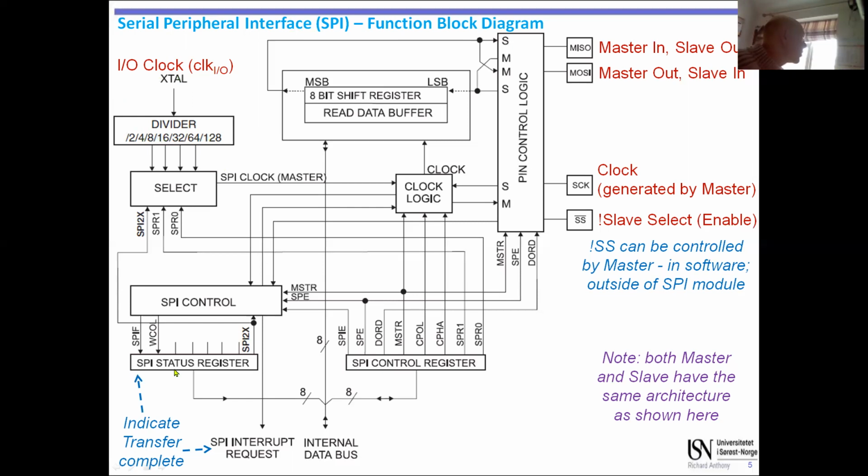And we've got the various configuration setups. This is where we set the main configuration, and this is where we see the status, what is happening. So we've got these various registers and flags, the interrupt request. It's all kind of the same. You get a pattern in the end. All these parts of the Atmel have the same basic operation with control registers and clocks and so on.